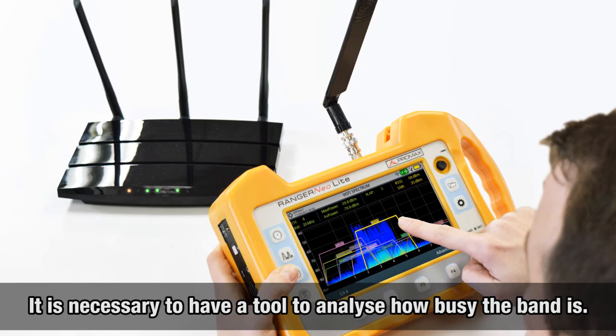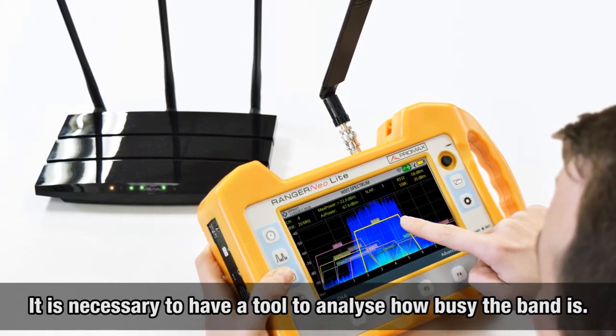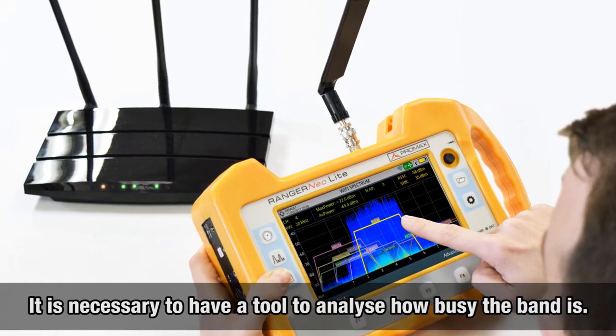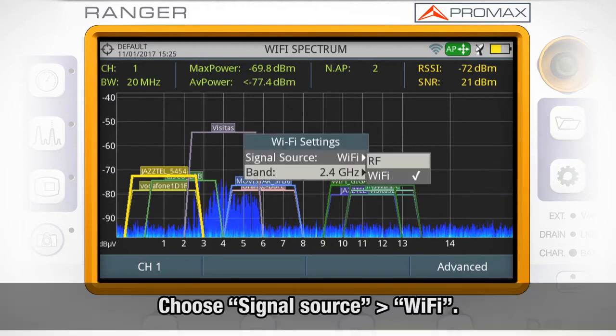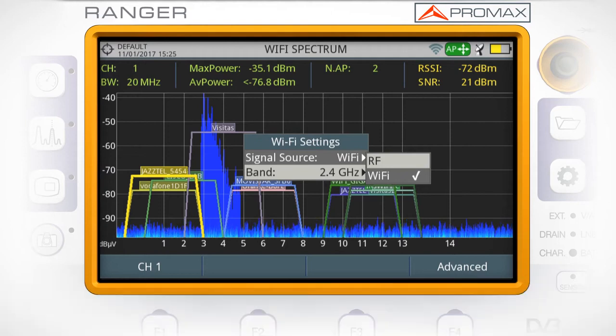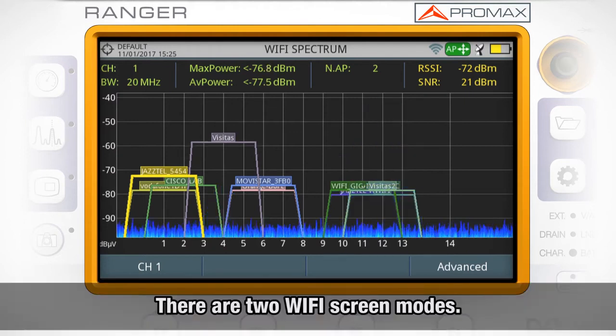And therefore it is necessary to have a tool that can analyze how busy the spectrum is with all these signals. To use this tool, we will go to the settings menu by pressing the wheel button and choose Signal Source Wi-Fi. The meter will activate its Wi-Fi adapter and scan all in-range Wi-Fi networks. Now we can access two different screen modes.